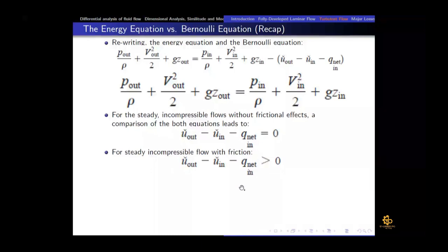So that's why the energy would be at a lower value at the end of the pipe due to those frictional losses. The energy which is coming in would have a little bit less value at the outlet of the pipe due to friction losses, because that part of the energy has been converted into thermal energy. So part of the flow energy has been converted into thermal energy, which increases the temperature of the flow, maybe by a few degrees or less than a few degrees. It depends on how much loss there is.